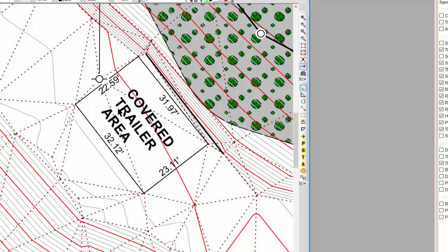So let's come in. Here's a triangle here right in the middle. Let's click it. Goes away. Here's a triangle over here near the edge, the corner of it. Let's click that one. And just for good measure, in case there's any contour lines that might come through this part of it, let's click that one. Okay, so you see how the tin lines disappeared? I expect that because those triangles are now invisible. And I just did manually the same thing I did earlier by selecting this traverse to exclude.